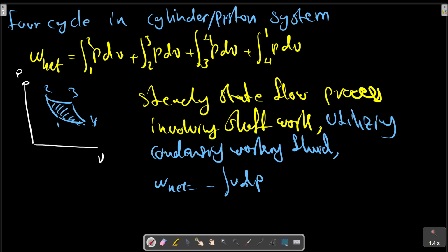In Chapter 12, we will consider systems utilizing a gaseous working fluid for both cases, a steady-state flow system with shaft work terms, and a piston cylinder system involving boundary movement work terms. In the next several sections, we consider the Rankine cycle, which is the ideal cycle for a steady-state process, utilizing a phase change between vapor and liquid to maximize the difference in specific volume during expansion and compression. This is the idealized model for a steam power plant system. The next section is the Rankine cycle.